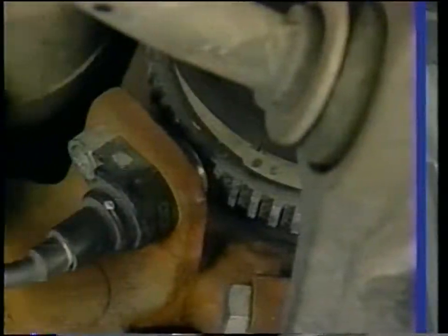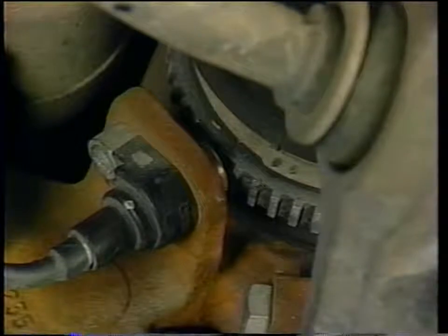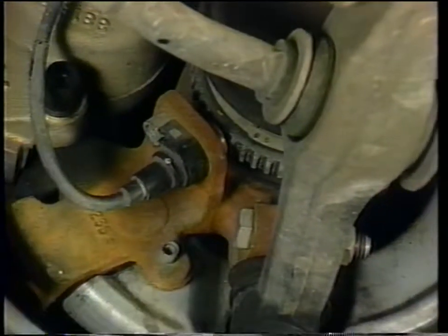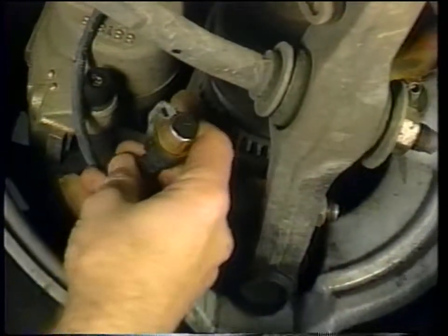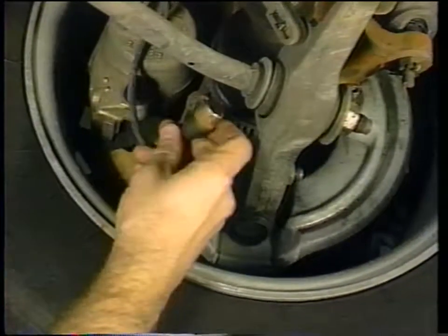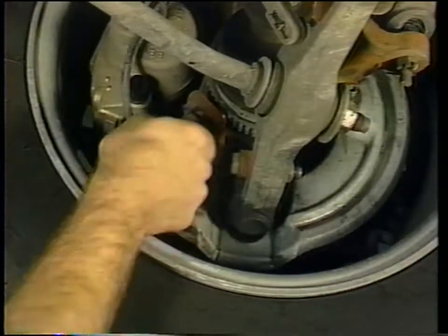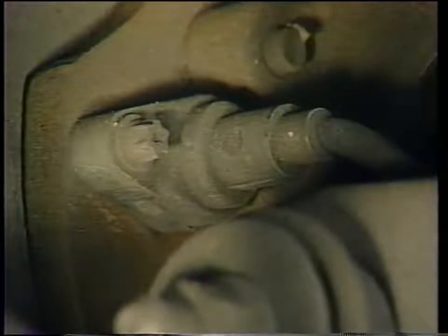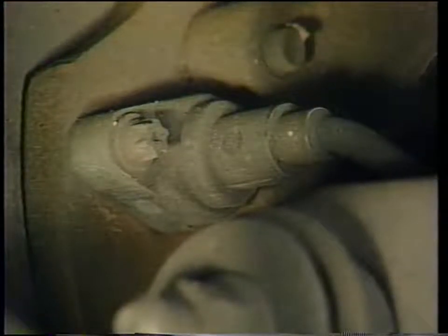The controller monitors wheel speed continuously through its 4 wheel speed sensors, which are mounted in the front knuckles and rear brake rotor backing plates. Front wheel speed sensors on Ford applications may differ in service procedures. Check the appropriate service manual for the correct installation procedure. Rear wheel speed sensors on Ford vehicles also have differing installation procedures.